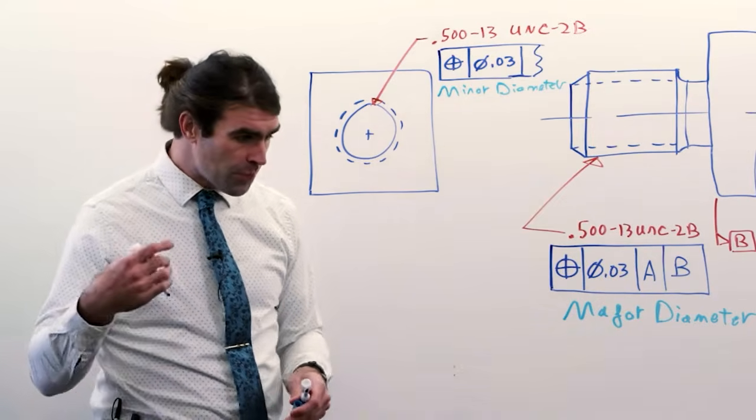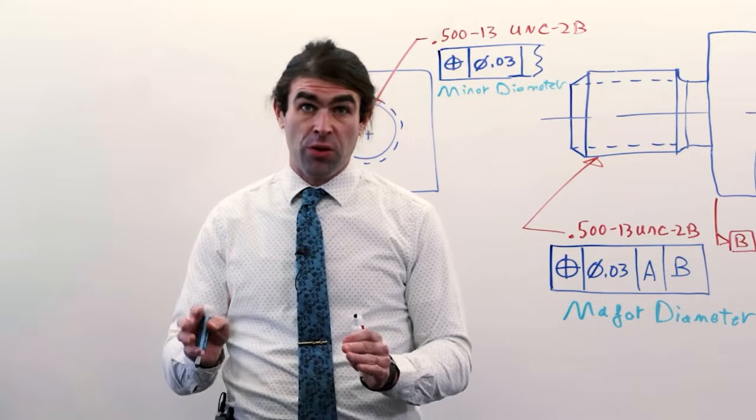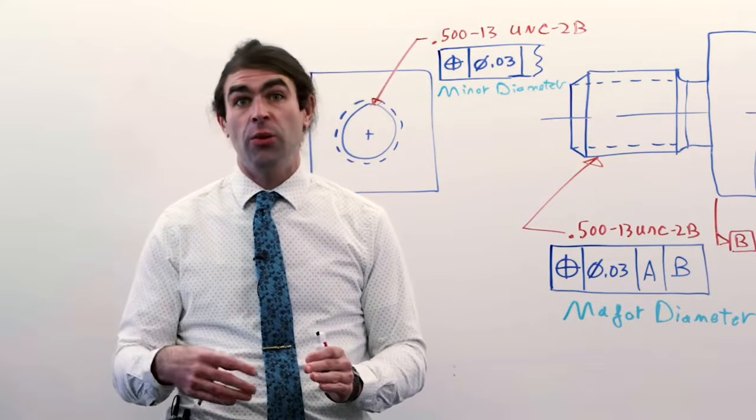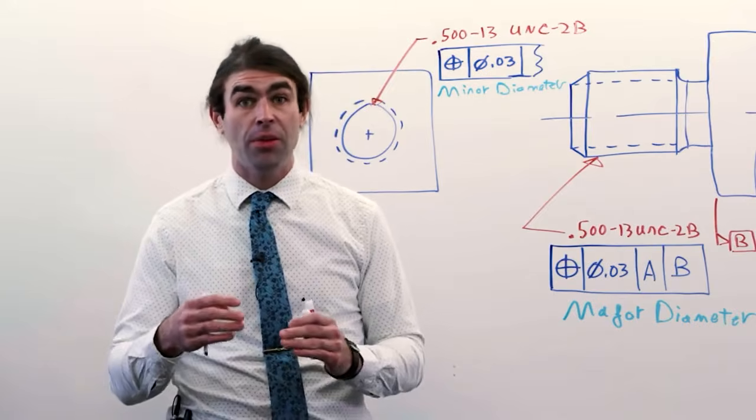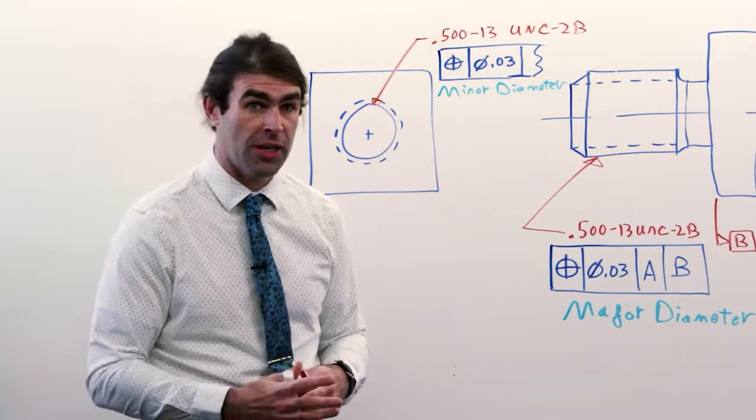So next I want to move to counterbores. Now, normally a counterbore is called out with a single position tolerance that applies to the hole and the counterbore. Let me show you what I mean.